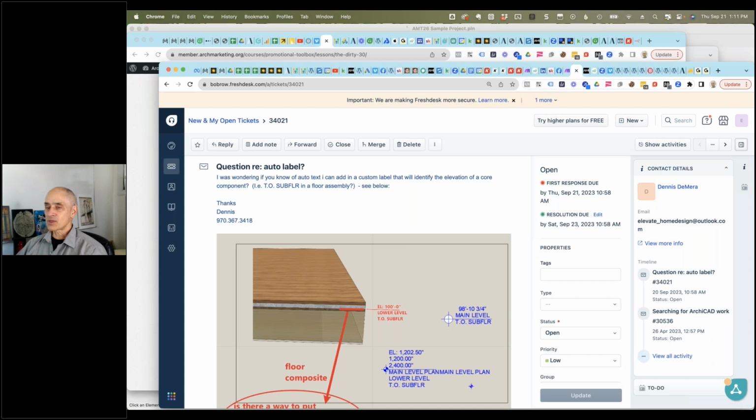So in terms of sloping concrete slabs, are you talking about slabs on grade that are sloped to make rain and things go away from the building? Both that and typical parking slabs sometimes. We have a workaround, but if you're just sloping in one direction, you can use a roof, obviously, and just change the material to whatever you need.